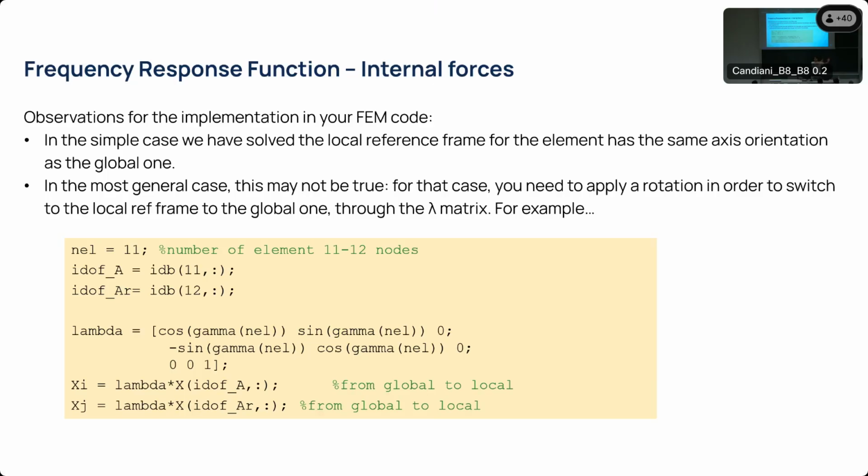So again, input force, frequency response function matrix, output displacement. If you want to have the acceleration, we derive it and we find the accelerations. If you want to compute the internal actions, then we go through the Euler-Bernoulli reformulation through the shape functions, and then we get output force. So always a chain of blocks of matrices and operations.